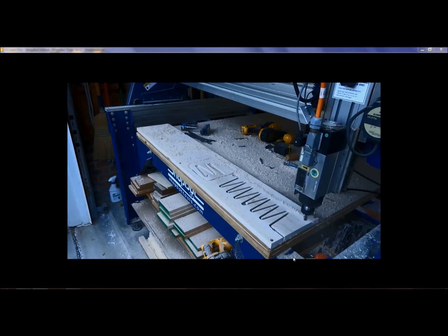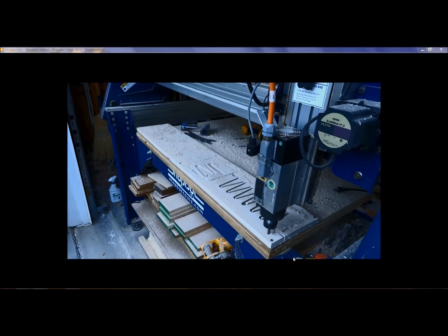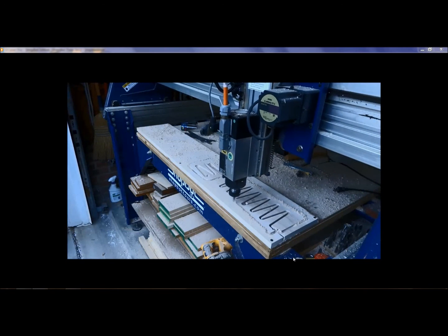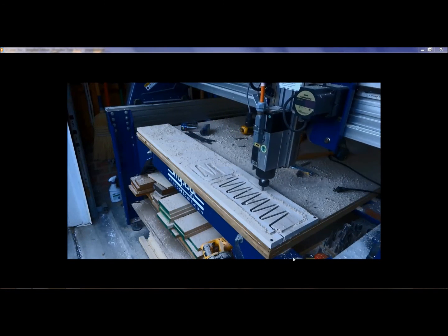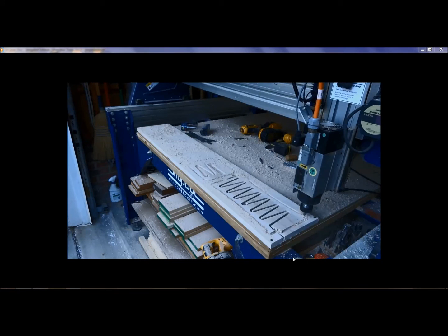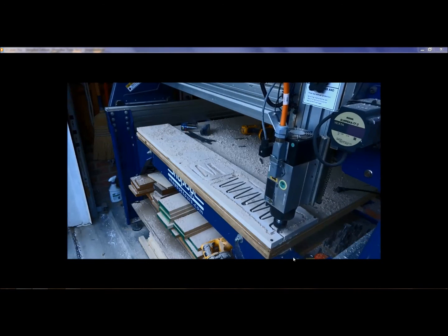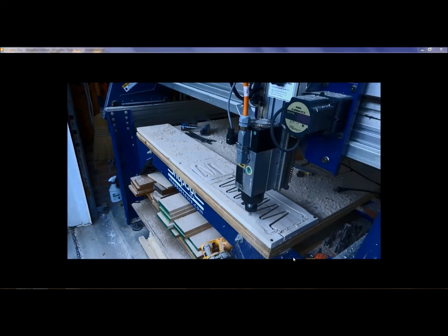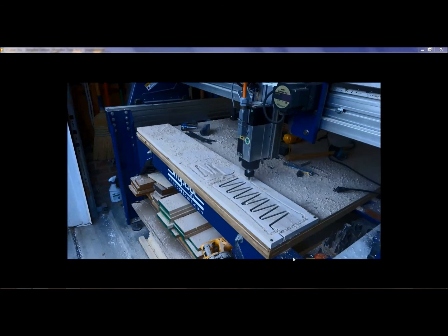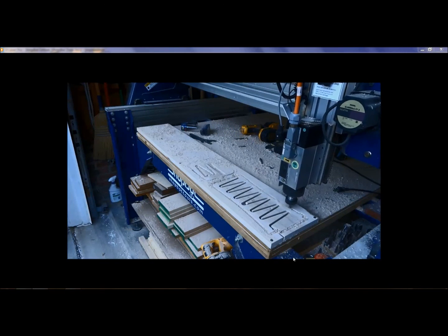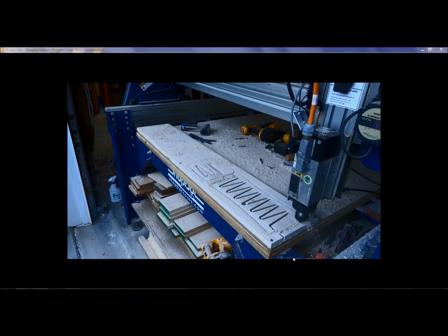That small little piece, without some sort of vacuum, could kick sideways, and that could kick right into the bit and tear out a good chunk of my project. So as you can see here, it's ramping down over the 4 inches, and then it's making 3 passes. I didn't want to exceed 3/8 depth on these passes because I didn't want to break the bit off going into this hard material.